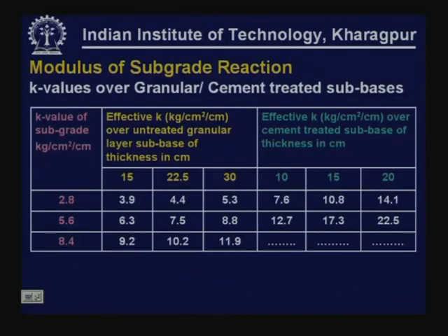But most of the times, especially for highways, we do not normally place the slab directly on subgrade. So, we either have a granular subbase or granular base or a cement treated base. So, the cement treated base plus the subgrade forms the foundation. There is a slab, and below that you may have 1 layer, 2 layers, 3 layers. All these layers below the slab form the foundation. So, we have to have one equivalent parameter, that is the K value, representing the strength of all 3 or 4 layers that you have below the slab.